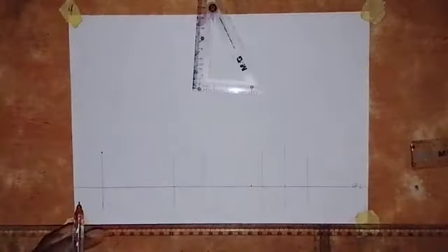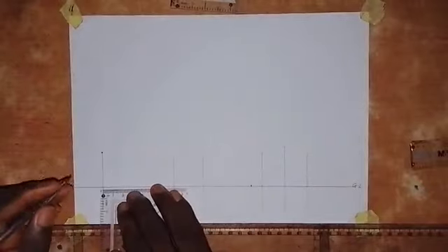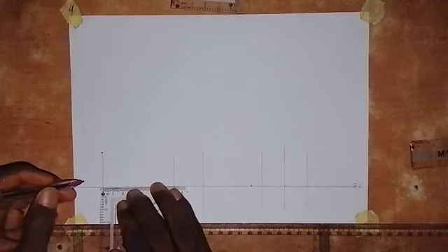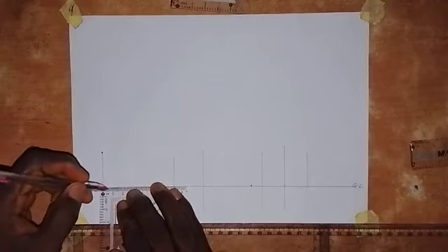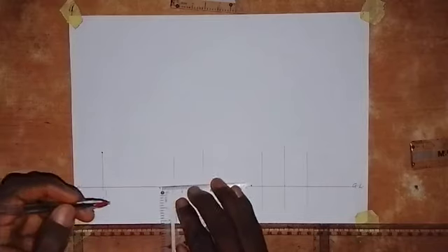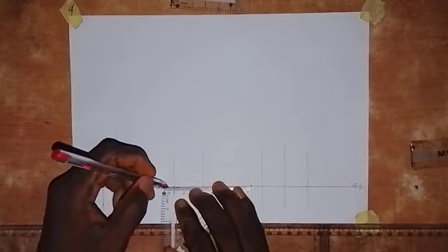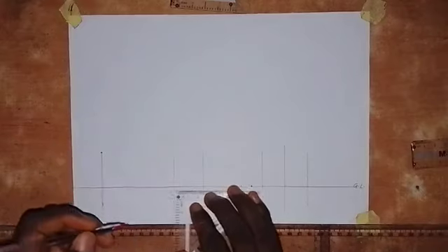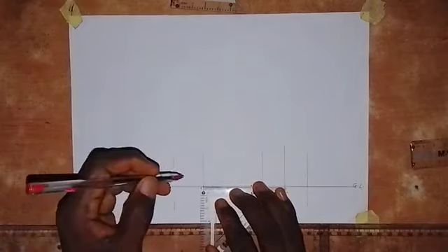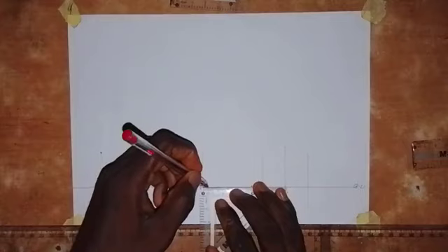So we are going to take a measurement of 5 millimeters from this. So this is an external wall. So we have to take that 5 millimeters. We take it inward. So this is 5 millimeters here. And then for this one, I will take this one to this side because we have more space on this side. So 5 millimeters to this side here. So we have this. And then for this, we have more space on this side. So I will take it in here as 5 millimeters. So this is 5 millimeters here.